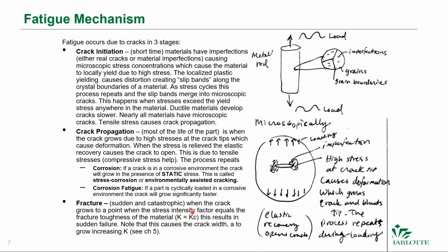Remember, the stress intensity factor is what we associated with the crack. We talked about that before. It's not the same as the stress concentration. When that stress intensity equals the fracture toughness of the material, then the result is sudden failure.